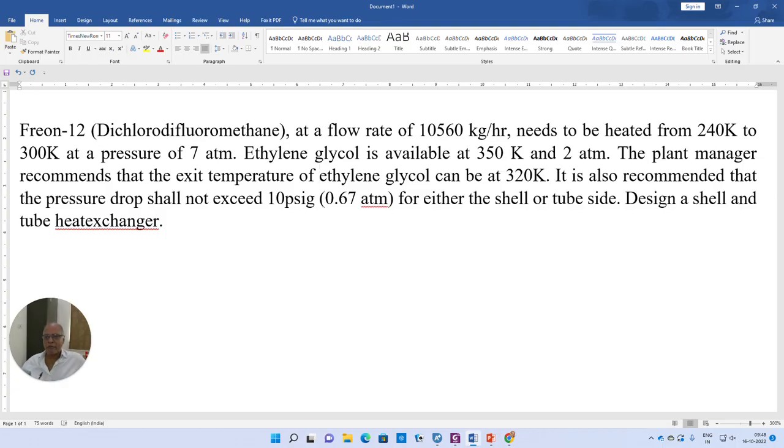This is how the design is performed. But the model that is available within Aspen calculates only the heat transfer area given the heat transfer coefficient. You will not be in a position to identify the dimensions like shell diameter, tube length, and baffles. Now, there is a separate module available within Aspen to do this kind of detailed design. This is known as Aspen Exchanger. I will demonstrate how to go about this design using Aspen Exchanger Design and Rating.